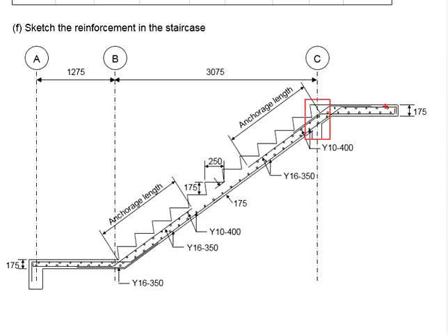If the beam is located here, now no part of the slab will be cantilever. Then the bottom reinforcement bars are important, and you make sure you provide sufficient reinforcement at the support to take the nominal negative moment at the support.